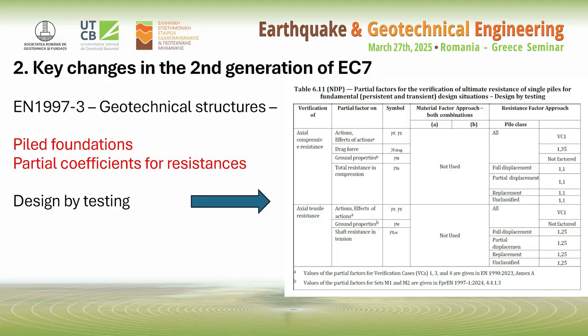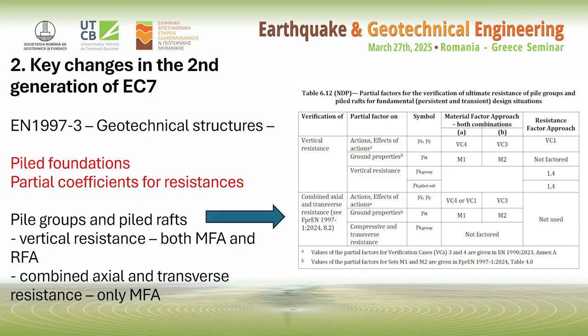And another one for the design by testing, again for piled foundations. For pile groups and pile rafts, there is a different table for the verification of the ultimate resistance. For the vertical resistance, we have again the choice between MFA and RFA, while for the combined axial and transverse resistance, only MFA can be applied.